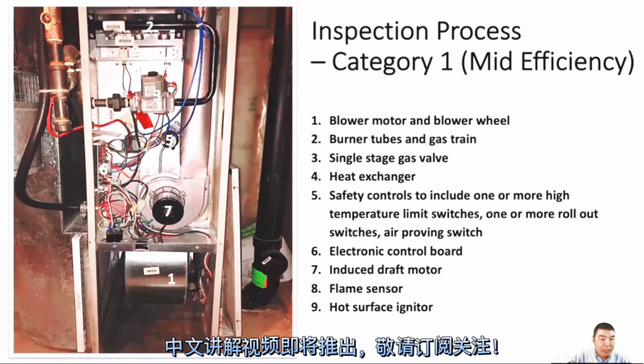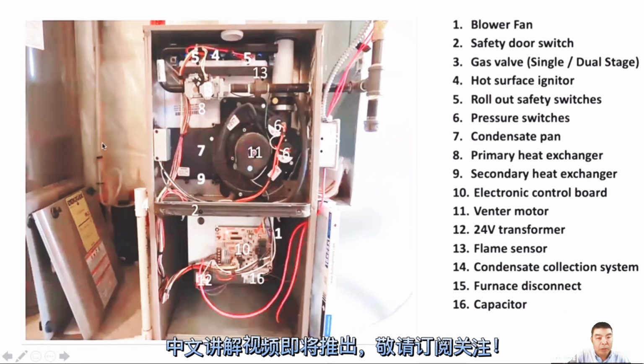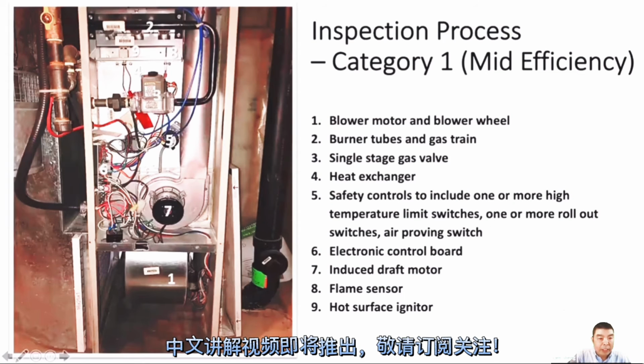Sometimes we can see dust or debris around the control board, especially if the control board is installed horizontally, on the top, and not vertically. It's easy to accumulate dust. If there's dust on there, it should be cleaned, otherwise some parts will overheat and then burn.